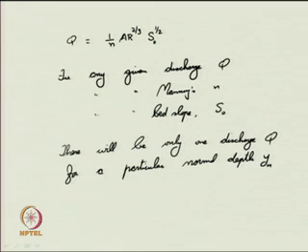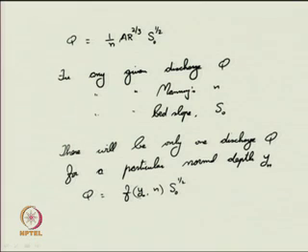This you have to keep in mind, as we suggested that Q is a function of y n and S to the power of half. So, for a particular depth y n, there can be only one type of discharge available. Therefore, vice versa, for a given discharge, we can have only one particular normal depth in that particular channel. That you need to take into account.